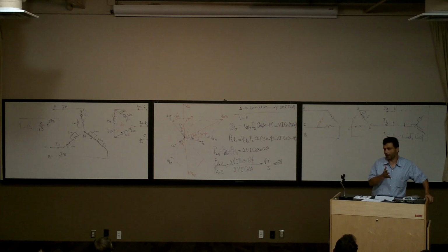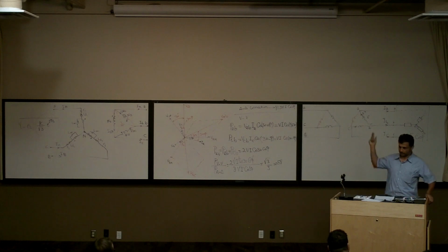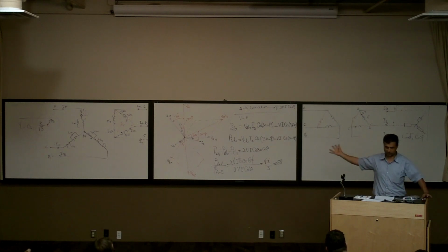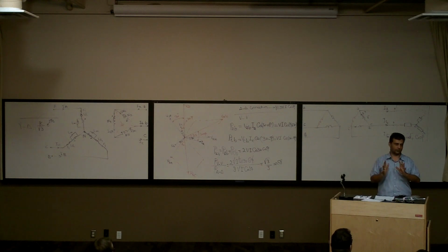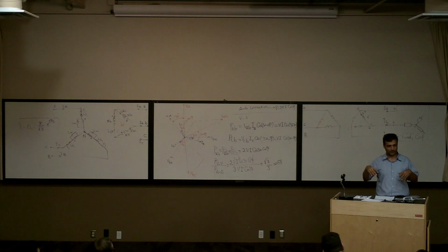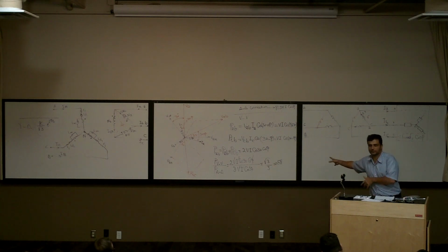That's exactly correct. Let's say there is a problem with one of the transformers, and I don't have a replacement for it. I have two choices. We have three single-phase transformers here, and one of them is not good. I can tell the load, I cannot supply you, shut it down. Or I can say, I can cover almost 60% of it.